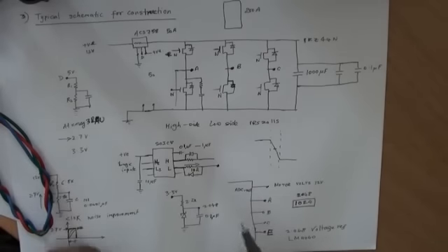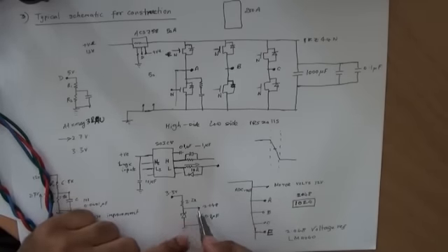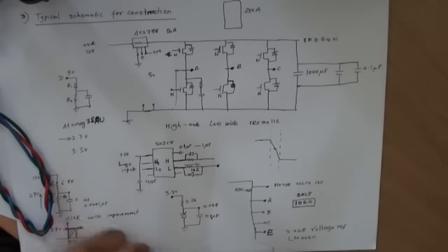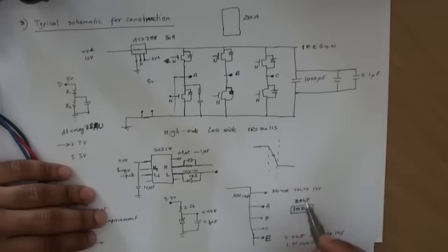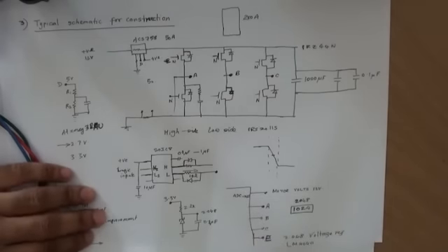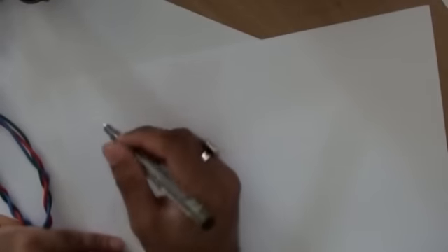And so if you connect a network like this to one of the ADC sources, you can back calculate your original ADC Vref level in terms of analog values. So rather than having it in terms of the raw 2048 level, you actually get an analog level for that. You do that by considering this.